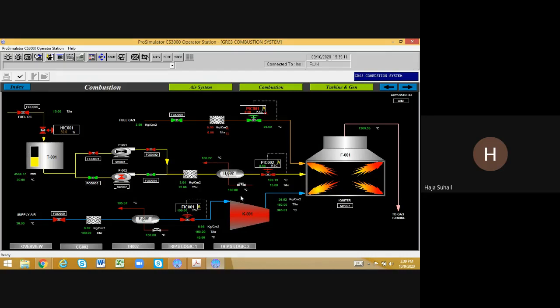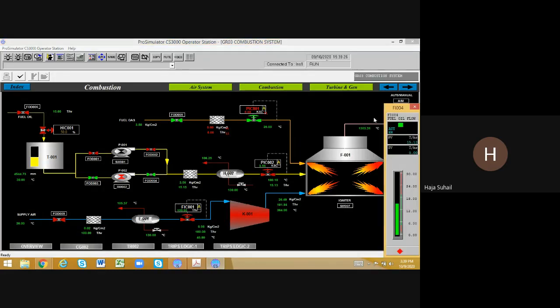So what is the title of the fuel amount which is going to the furnace? I have to know the indicator number ID. Since it is showing down, I'm clicking here and you can see the title of the indicator. So the fuel oil supply which is given to the furnace is F5004. Okay, we have to select that one.